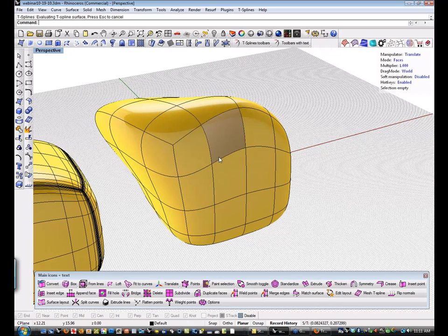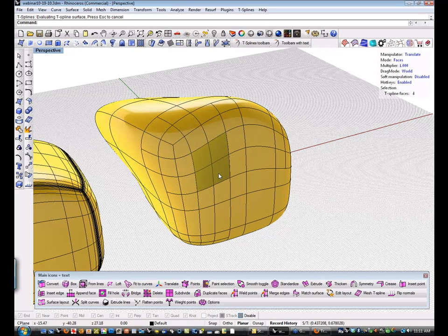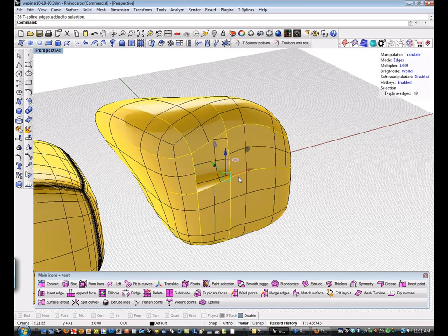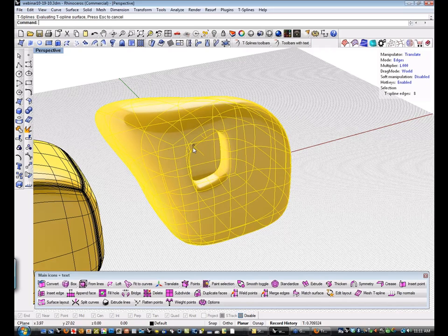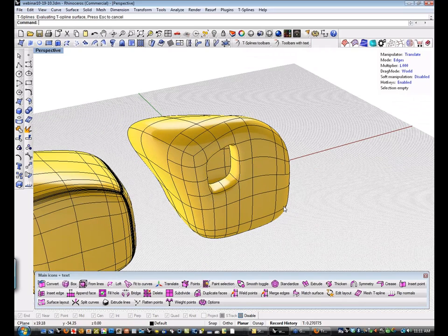But then that allows me to come in here and subdivide these further and make a hole here. It's going to shoot creases through the model. Pick an edge here, here, here, here, hit the L key to select those, and extrude. It's only going to extrude the exterior edges, and I can put a loop right there in the center.